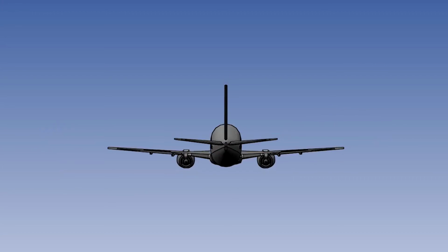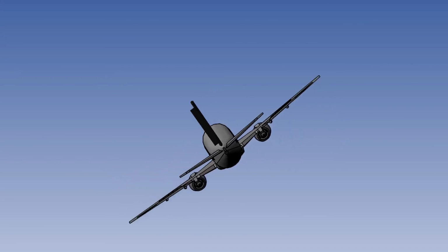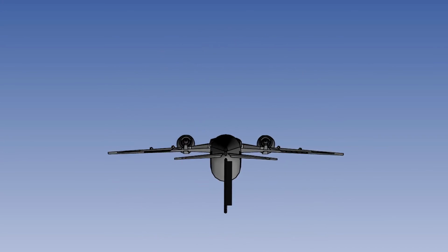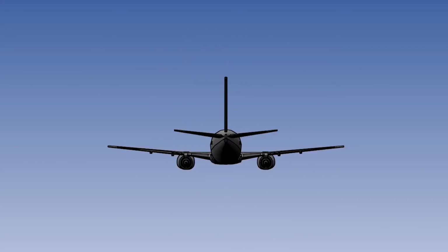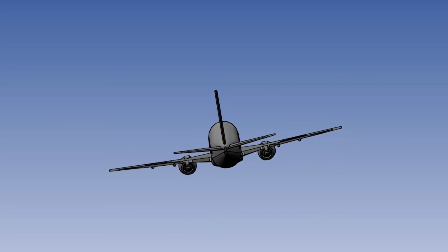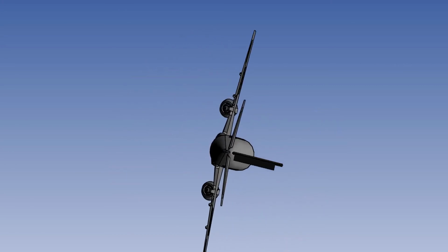The use of rudder has already been mentioned in the earlier section on stall recovery, with its attendant risks. A coarse application of rudder before the wings are unstalled to pick up a dropped wing, but inadvertently in the wrong sense, in the direction of roll, could put the aircraft into a spin. Even if the rudder were applied to oppose a wing drop, it would require a large rudder deflection, which could well cause a spin in the opposite direction.